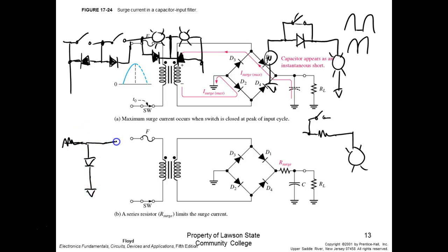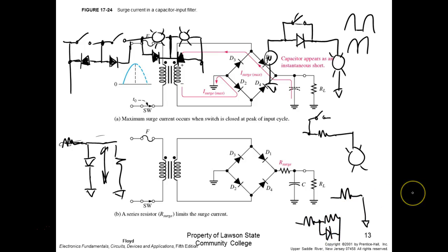So what would happen is when this is reverse bias, then you have this series circuit, right? When this is forward bias, this guy right here is shunted across. So you switch from a circuit that looks like this to a circuit that looks like this. So what happens is on your positive alternation, you bypass the second resistor.